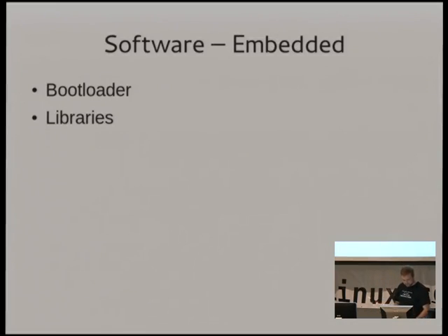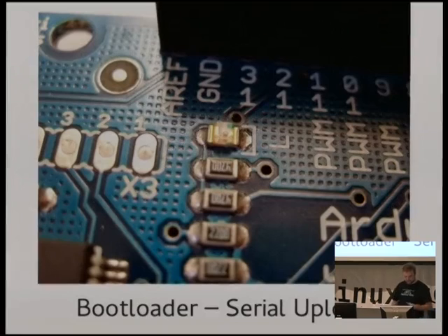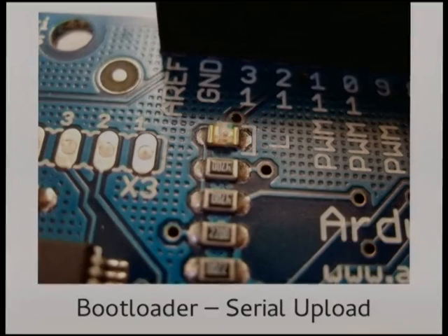So the embedded software I've mentioned before is the bootloader and the libraries, and the thing that the bootloader gives you is the serial upload. You might have noticed sometimes, especially with the newer boards, if you've actually got an application running that uses the serial port, when you plug the Arduino into your machine, if the Arduino's got an external power supply and it's already running, you plug it in and it resets itself.